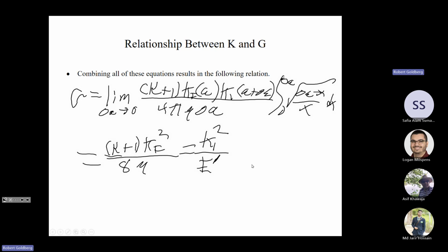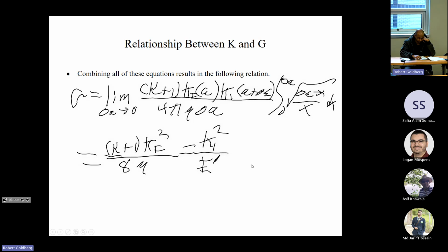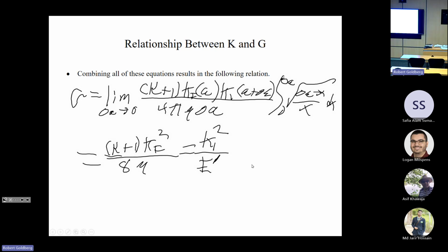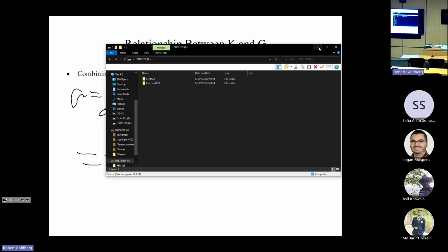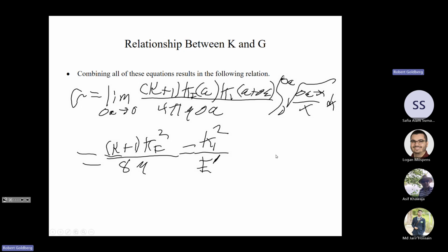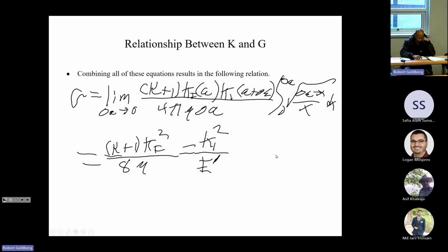The point is, it's kind of an esoteric analysis, but we ended up with that same expression we got originally for the relationship between the strain energy release rate and the stress intensity factor, so we can make a reasonable claim that this expression is true not just for the case of an infinitely long plate with a through crack.